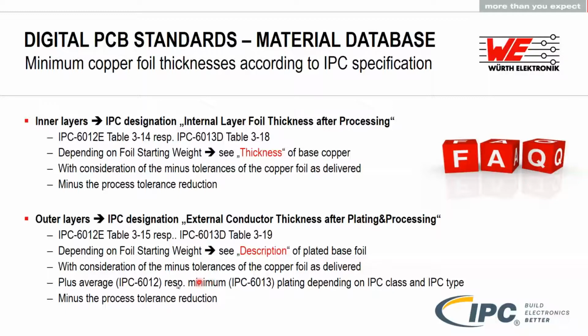So for rigid and HDI boards, there is the average plating thickness, and for flex and flex rigid PCBs, we have to consider the minimum plating thickness. Again, minus the process tolerance reduction. So now we have a closer look at the tables.